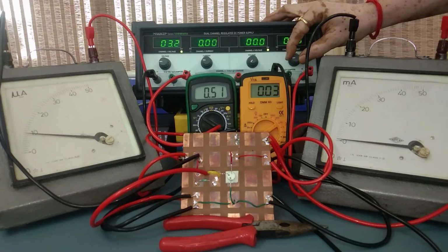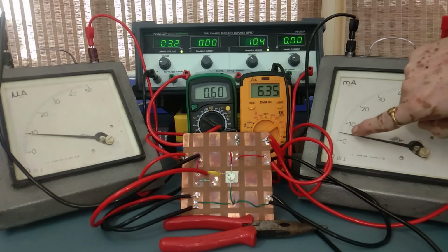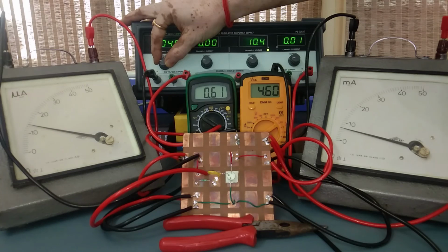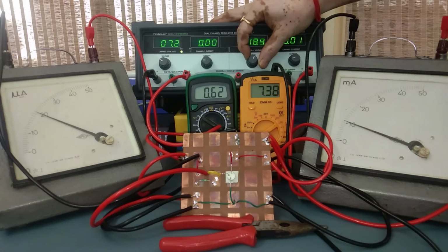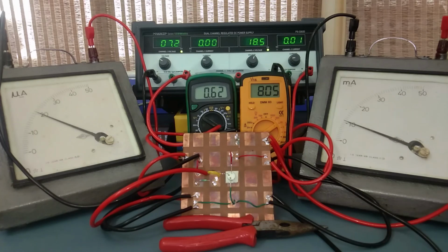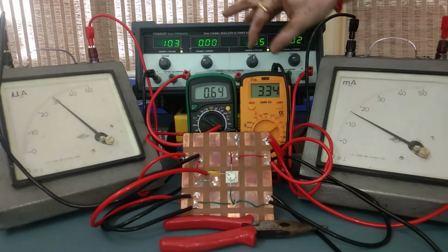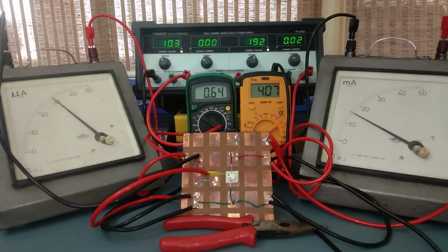Okay, and let us now try to see what is the constant value of current. You can see here it is somewhere around 4 milliampere. Alright, now I will change this to 20 microampere base current, and you can see the current is increasing. Now you can find almost 10 milliampere is the constant current. Now I will be increasing the base current, and you can see this constant current value has increased to 15 milliampere.